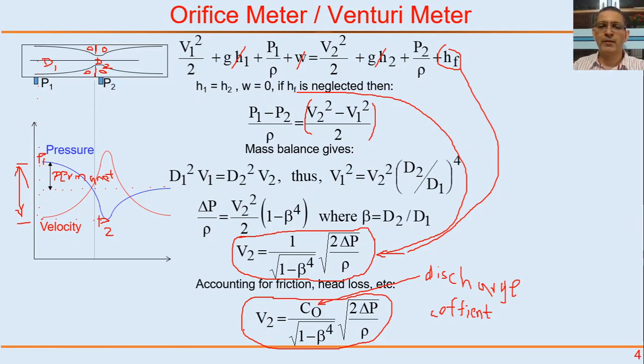You could have written this as flow rate being proportional to square root of delta P by rho, and that proportionality constant is our discharge coefficient of the valve, or the valve coefficient CV. Open the last lecture and see this for yourself. It is one and the same.